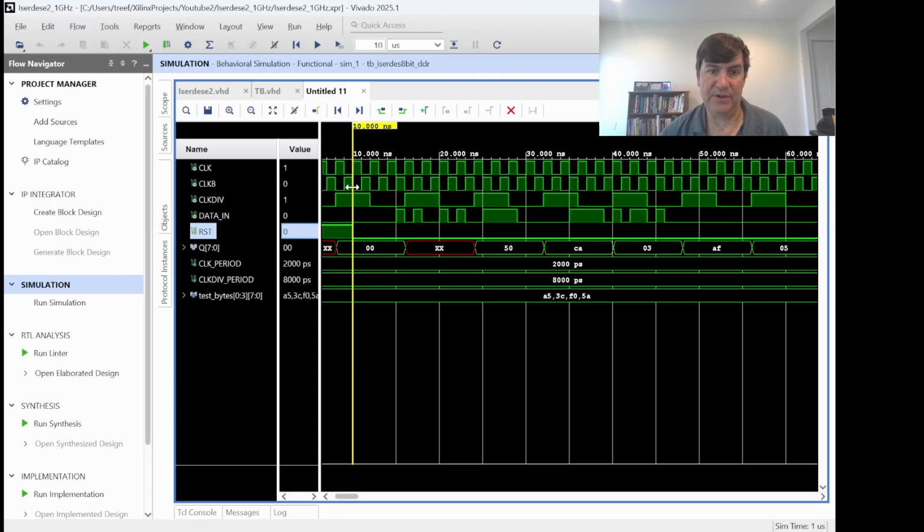Here we're coming out of reset on the rising edge of the streaming clock. But all I changed was the divided by clock, and I inverted it. And what that did is it made this into a collision, which you do not want. This will cause you problems.